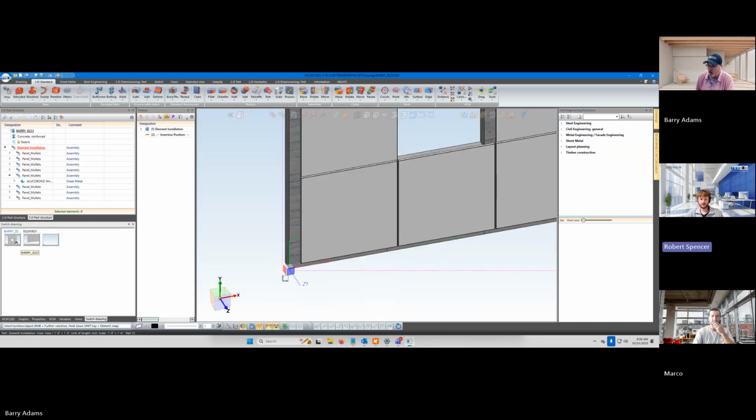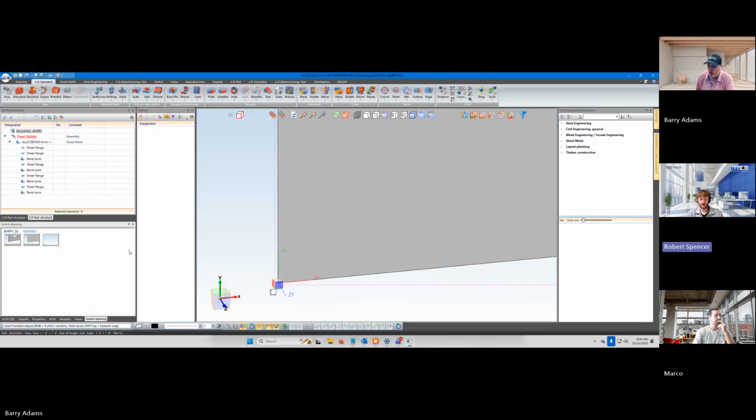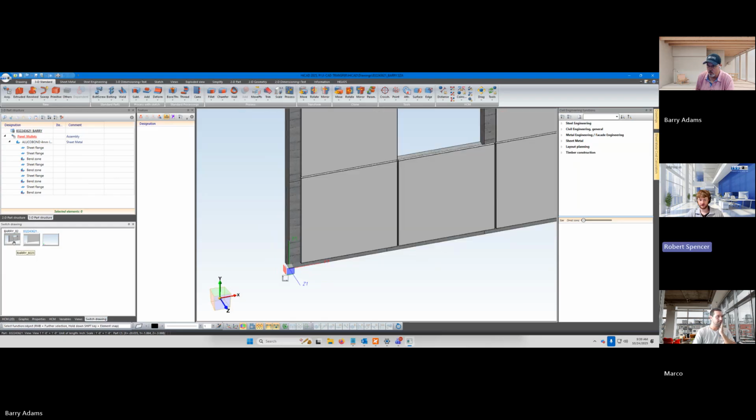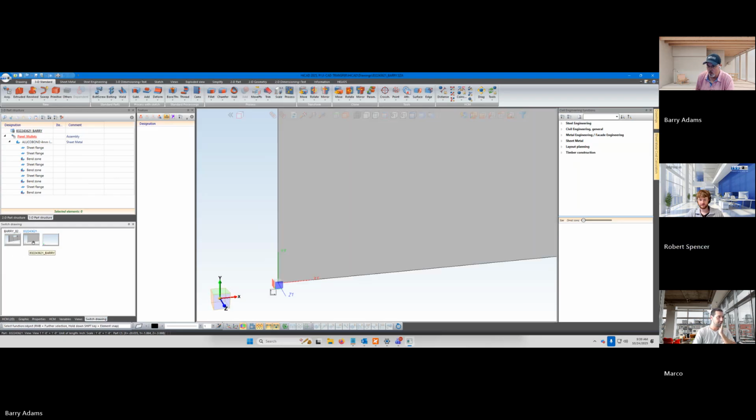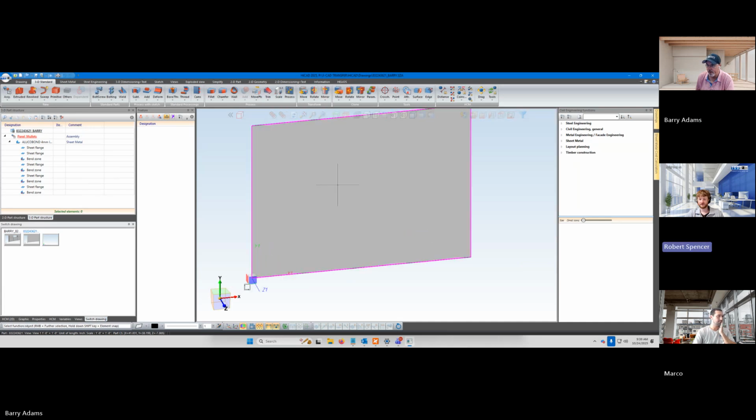Before we do that, remember we made a change to the panel, so we need to resave that to the library before we update the elevation. It's not a live link. So you have a part file, you prepare your panel, and you save it, and you apply it to your elevation model.